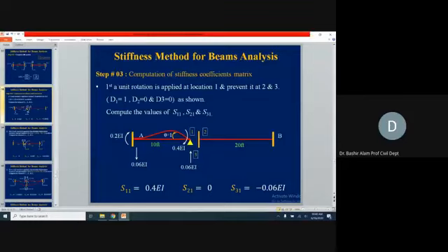At the far end, it will be half of this, so 0.2. And this is 6 EI theta divided by L square. So this is the couple, which are the vertical reactions at A and at the hinge. At the right hand side, we don't have any activity, and it is not going to let the moment transfer here because it's a fixed support here.